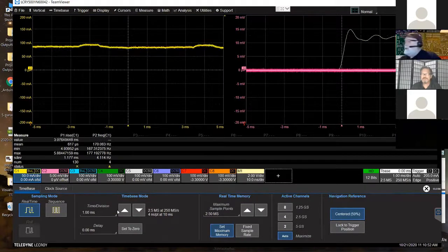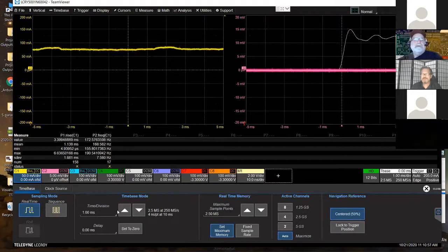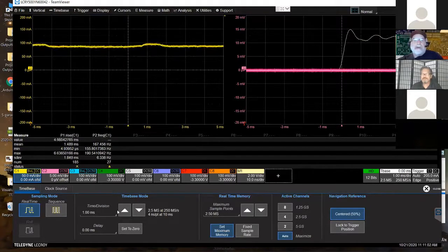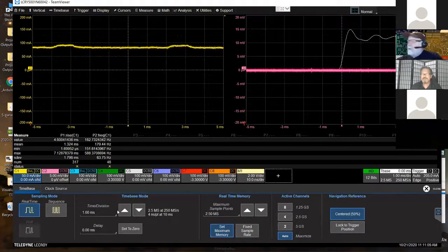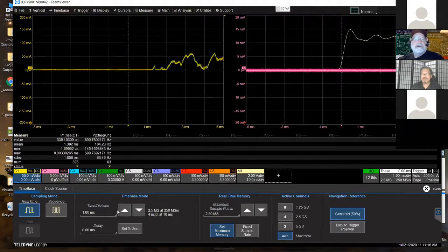So all I did was connect the output shield of the USB, which is the ground connection, to another ground source. So they're all ground, right? Everybody's plugged into the power rail, or the neutral line in the lab, they're all connected in there, and yet, oh my gosh, we're seeing this large amount of common current, 100 milliamps of common current in that cable. And if I go to another source of ground somewhere else, I can see another amount of noise on that.